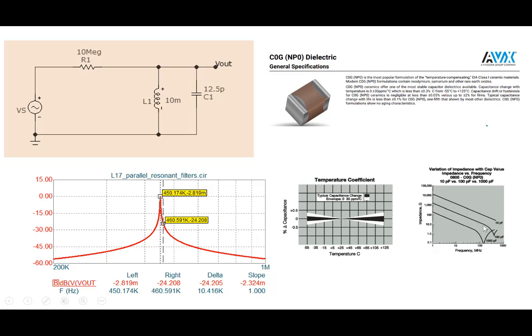You do get it. It acts like an ideal capacitor over this range, but note that here is where there's a shift. It's no longer capacitive; at this point the impedance is actually falling to 0 and then becoming inductive here. And here also it is going from capacitive to inductive. So all capacitors have leads, and leads have inductance associated with them. They have some resistance associated with them.